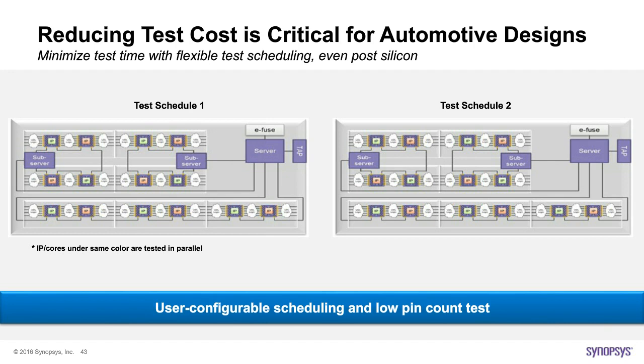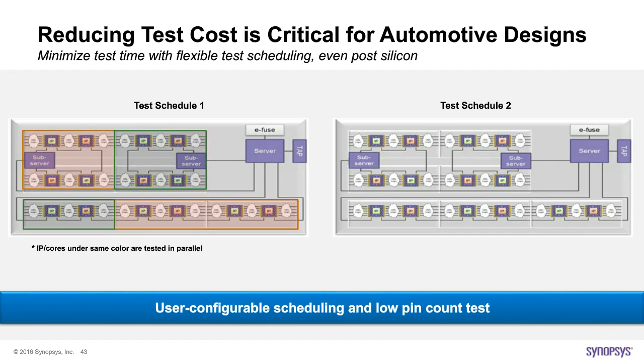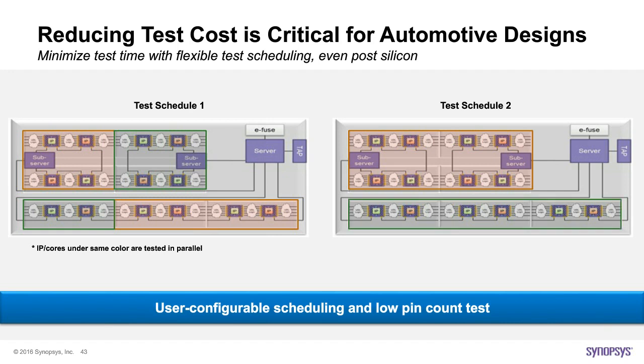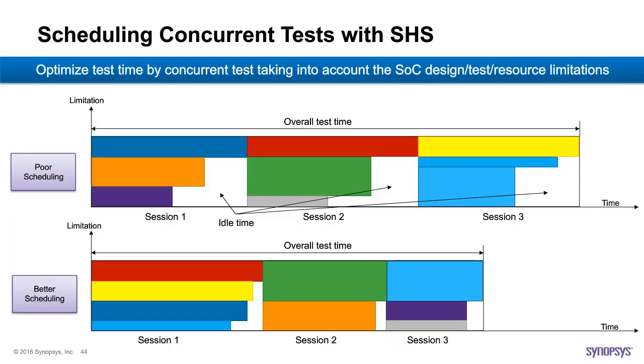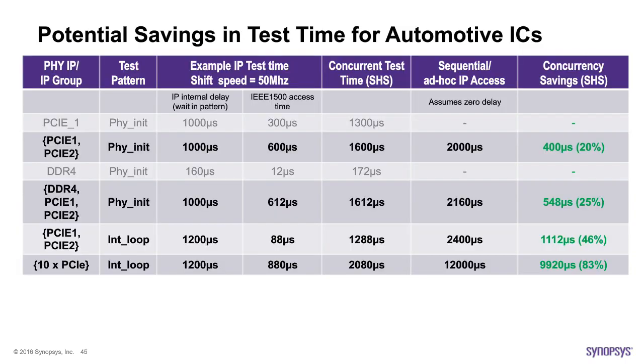So scheduling, test time, power, as well as the functionality can be of different sorts. I could do these together, or I can do it in a different way. So the same SoC can have multiple test schedules depending on the needs. In production mode, the need is the shortest test time for the entire SoC. The power on self-test mode is the test and the repair with power on in the system. Then if I move on, in the mission mode, I have different composition, and the time is the most critical one, which I need to meet.